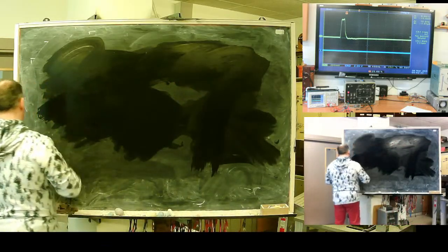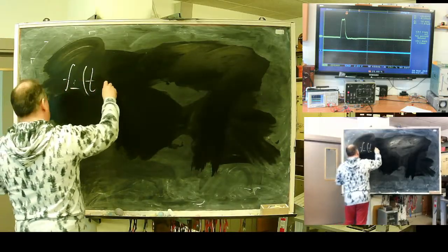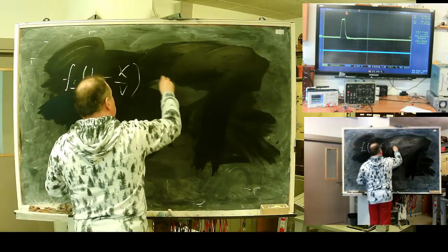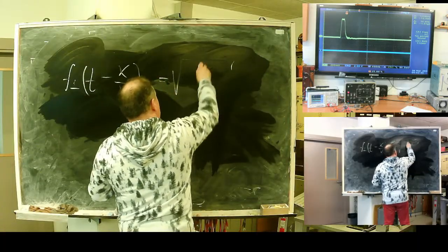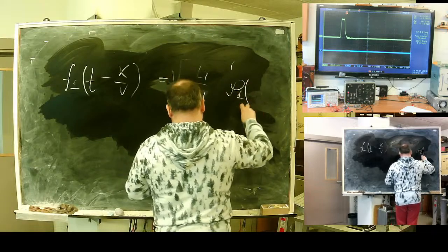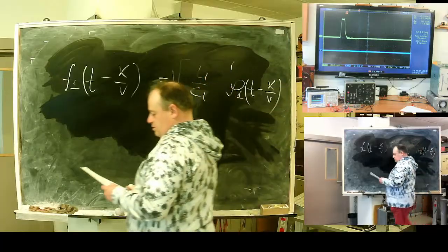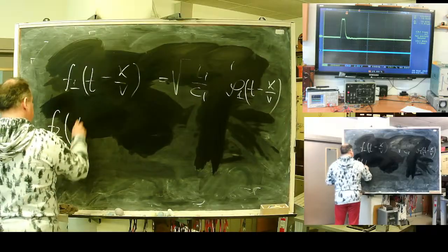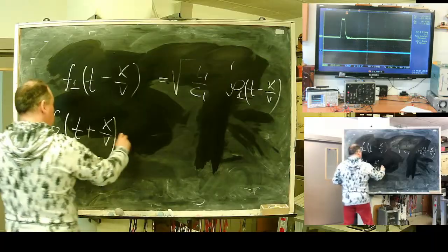In any point of the line, the value of the direct wave voltage equals square root of L1 over C1 times phi1 of t minus x divided by v, because Ohm's law is still in charge here and should be obeyed.